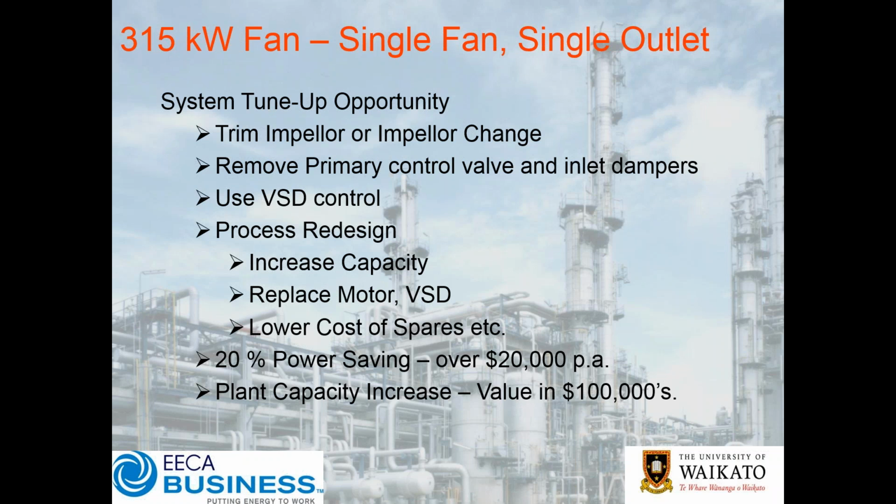So it really depends on the application, but this is where, like I said a few minutes ago, having a very good relationship with a good quality fan supplier becomes important, because assuming that you've done some good system measurements, you're going to know what flows and pressures you want, i.e. you're going to know what your system curve is, and then it may be that my fan curve is nothing close to what I need in practice, and so that might need to be changed.